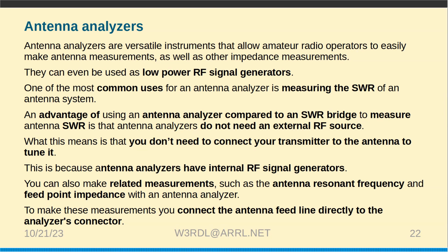It's got a low pass, a high pass, a band pass, a BSF. It's a notch filter. What's BSF? Band suppression filter. And it's got a couple of SWR loads, a 33 and a 75 ohm. So you can look at all the stuff on the Smith chart, and then it's got a bunch of reactive series and parallel tuned circuits. So you can kind of do all of it, it's already built.